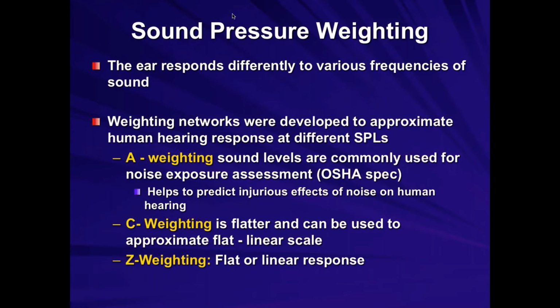At 90 decibels, you start to get to the point where you have to provide hearing protection and you have to limit the worker's exposure. So OSHA says you can't expose a worker to more than 90 decibels of noise over an 8-hour workplace exposure.